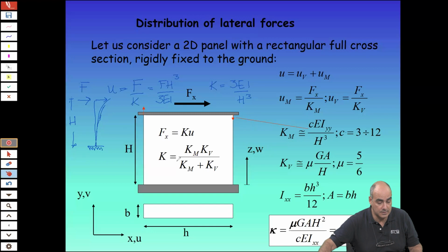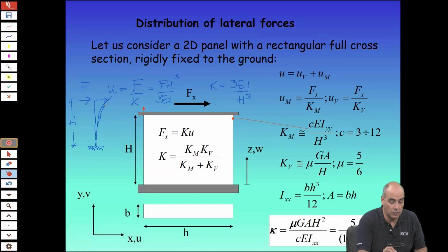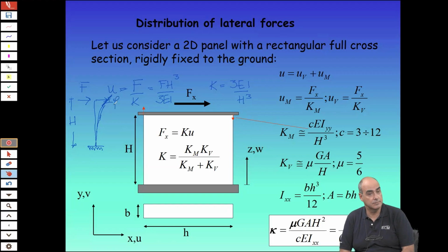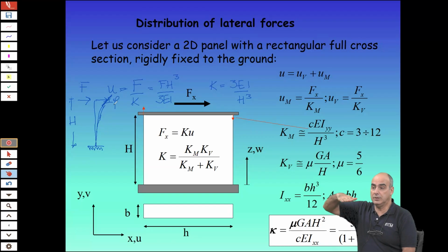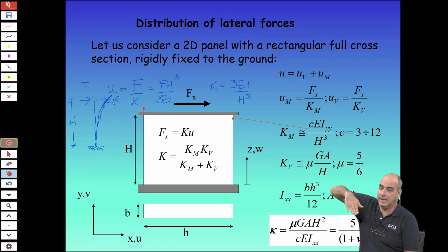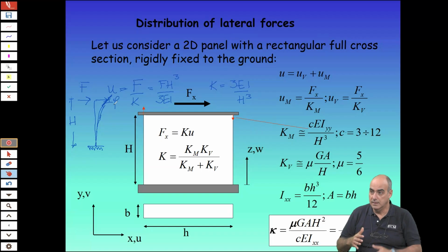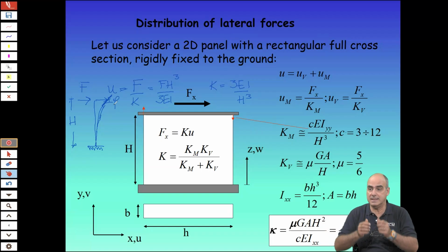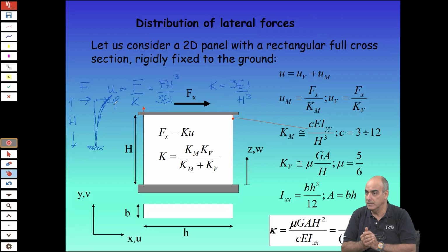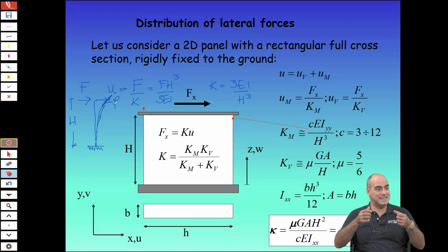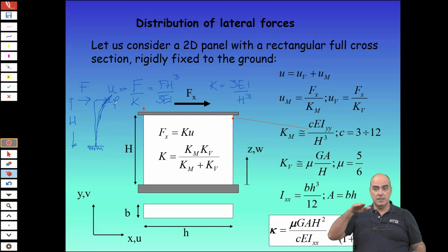also implies a rotation here at the top. Rotation at the top means that your floor should do a movement like this. But this implies that all the elements of the system will go under tension and compression. Actually, this is very difficult to achieve because the elements, the columns, are very stiff in the axial direction. So the diaphragms rather move horizontally and do not rotate.